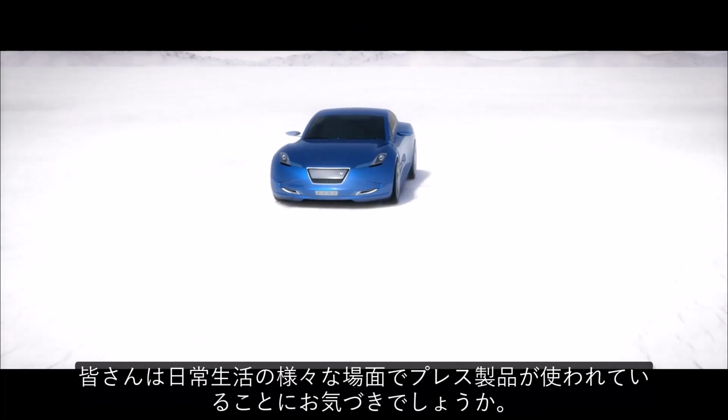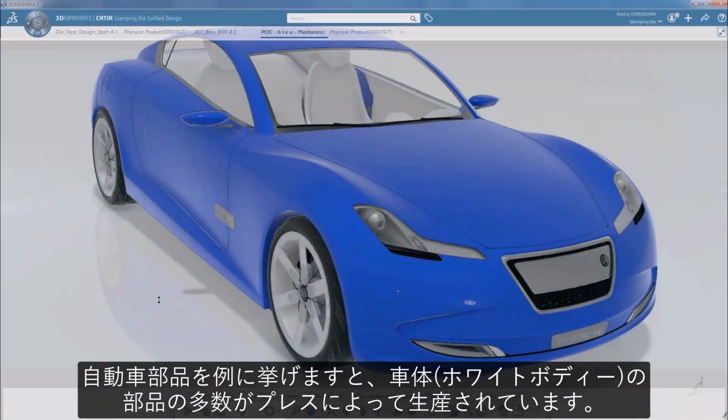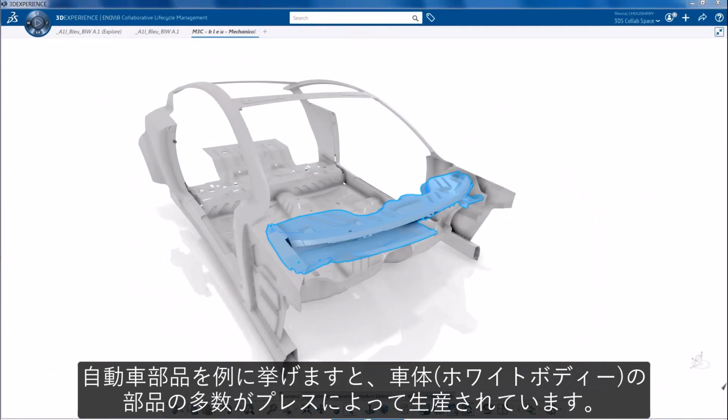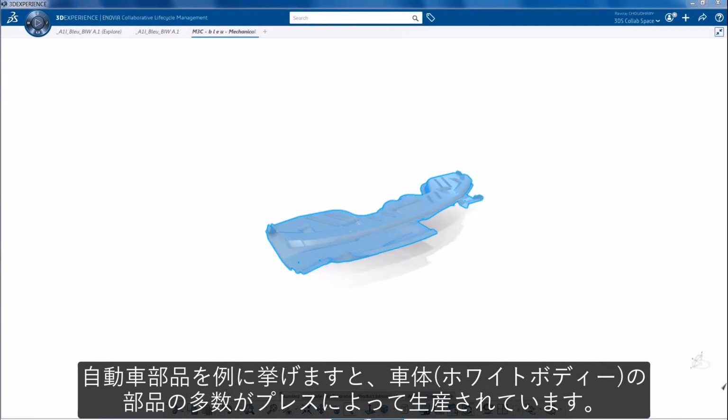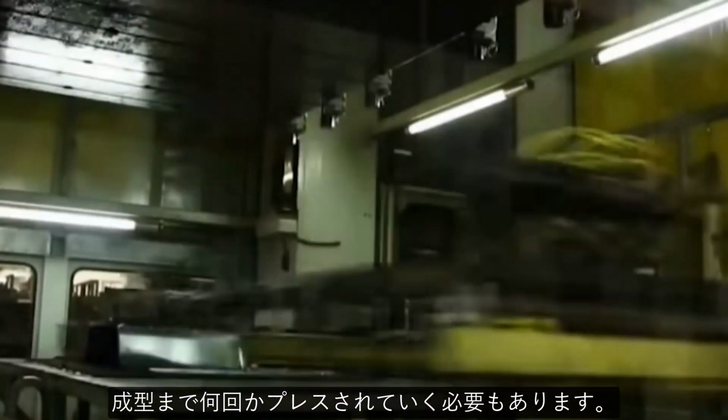Before we begin, stamping components actually live in many corners of your daily life. For example, the cars. The main body or skeleton of a car, or white body, is typically made of an aggregation of metal components that are manufactured with stamping. Some of the larger components, say a fender, would need to go through multiple stages of stamping processes to reach the target shape with desirable aesthetics and optimal quality due to the nature of its material.